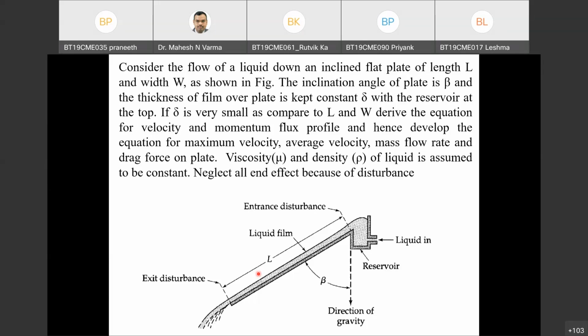We are considering momentum flux. Density is constant, so it will be an incompressible fluid. Yes, very good. So you can use the simplified form of Newton's law of viscosity. Only the first bracket is important. For an incompressible fluid, the second bracket equals 0.